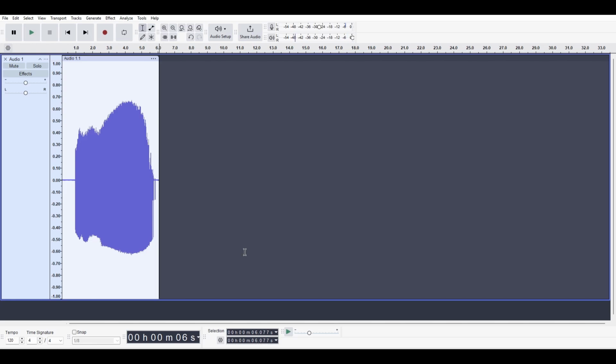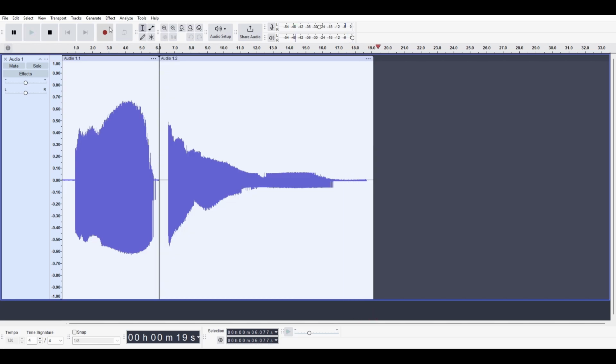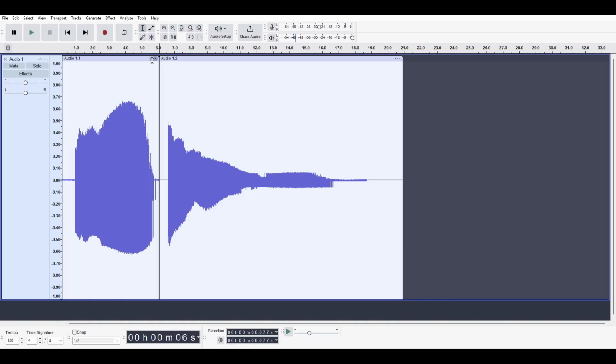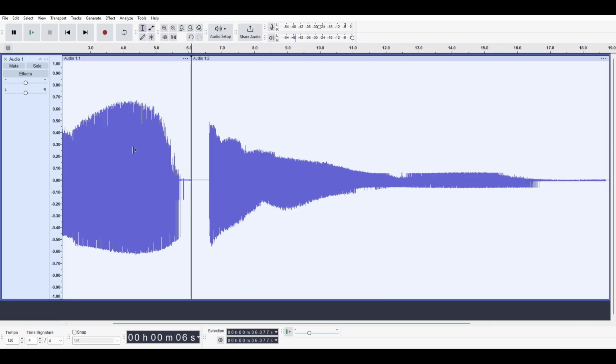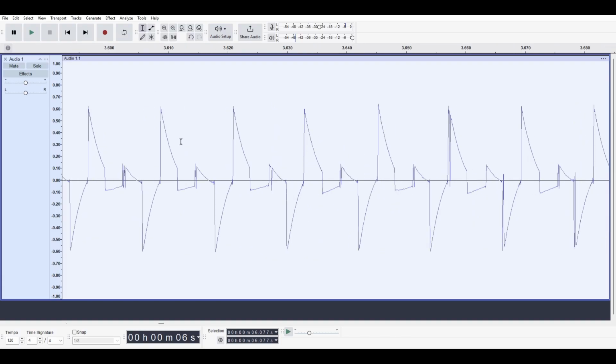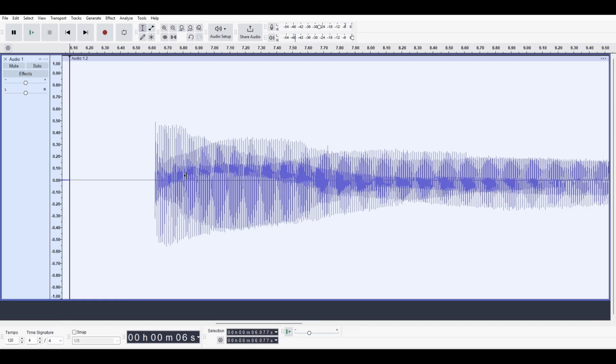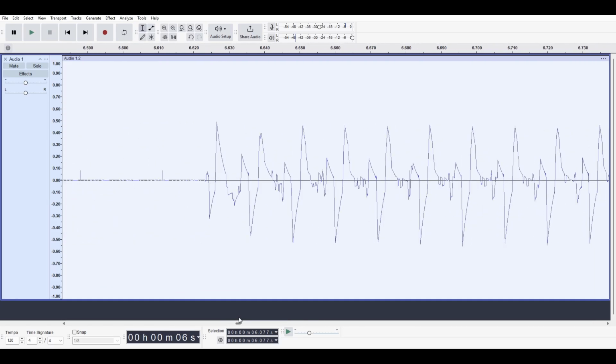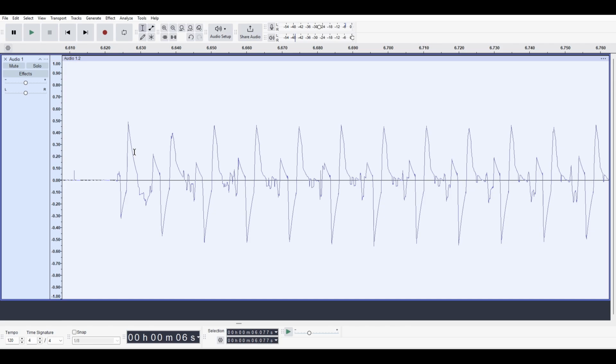So if I click record now, you can see that in the old design the signal got louder when it was fading away, which it's not supposed to do. And that was because if we zoom in here, somehow some of the last bits from the signal were contributing way too much voltage. I'm actually not using any capacitors in my circuit, but my audio interface probably has an AC coupling capacitor, and that's probably why you get these exponential decays here.